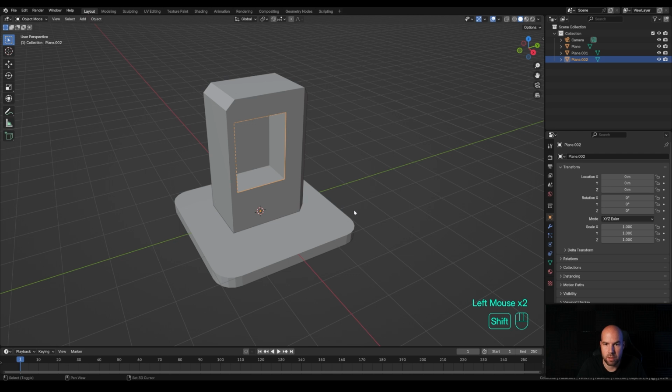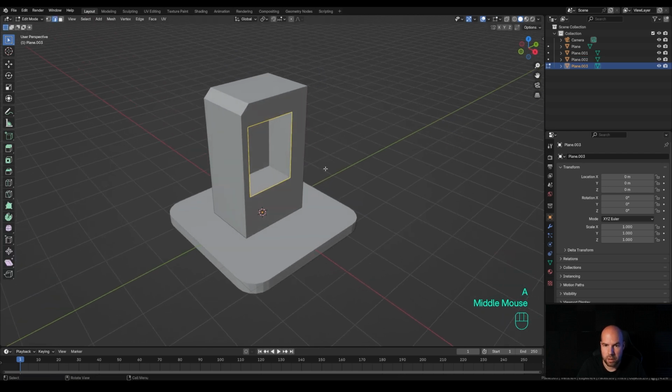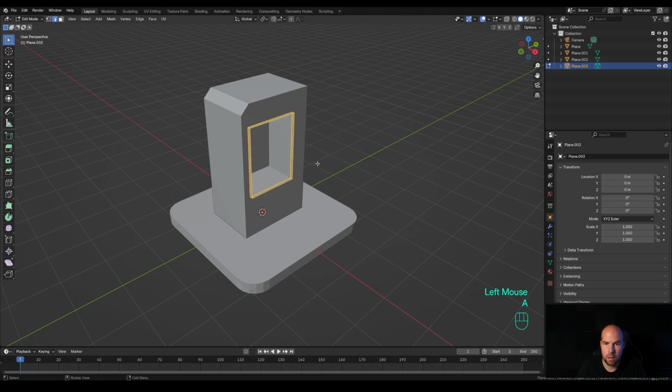all let's duplicate it. So press Shift D, tab into the edit mode, press A and now extrude, so E then X on the X axis like this. Now press A to select all. First let's recalculate the normals, press Shift N and then Alt E and extrude along normals like this, and we can press S to scale evenly, just like this. And now again press A and Shift N to recalculate normals. I always do that when I'm extruding from a planar geometry.